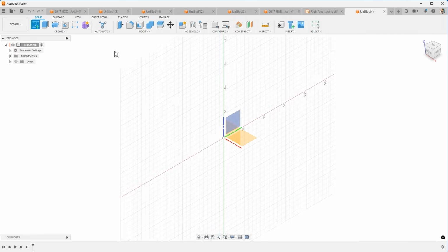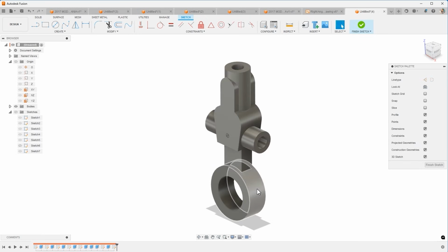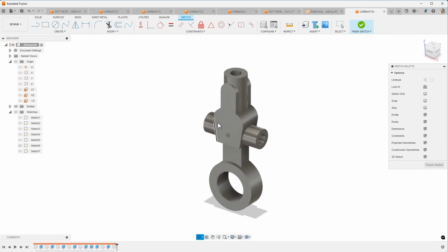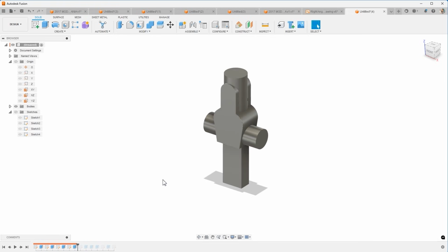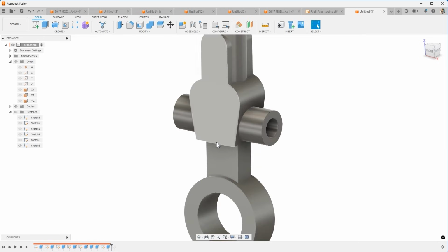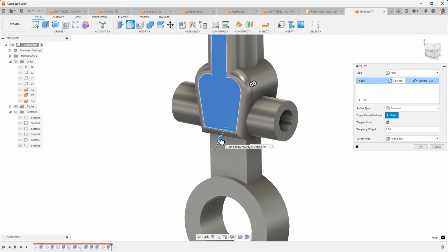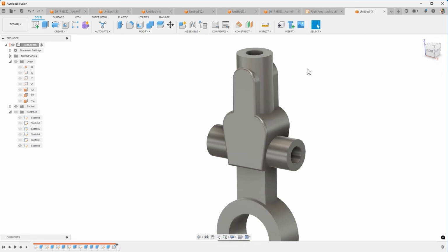In fact, what you want to do is try to create all of your solids in steps. So instead of trying to do this all in one hard feature, this is pretty overwhelming and complicated, but in reality, this is really just a series of extrudes, right? So we're doing all the solids first, and there's a reason for that. The cuts happen to intersect with each other. So it's a little easier for me to create all the solids and then come back and introduce all the cuts at the end. And then finally to introduce the fillets at the very end, those finishing touches, so that those aren't being impacted by cuts and additional solids as well. So good rule of thumb for Fusion, do all your solids, then your cuts, and then your finishing touches at the end.